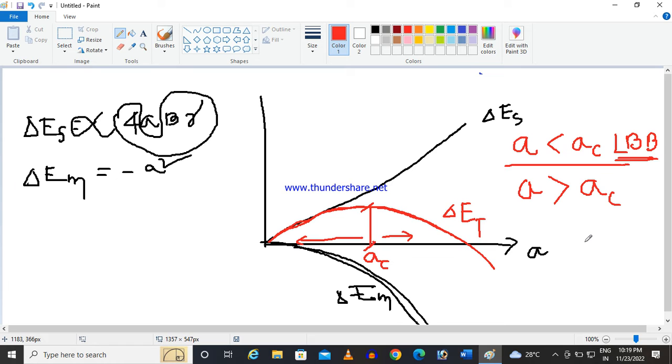Okay, so during the design you should consider these two things. So definitely, if there is a crack, that always should be lesser than the critical crack length of the material, based on the material property, which is given in the ASTM standard. We followed ASTM.